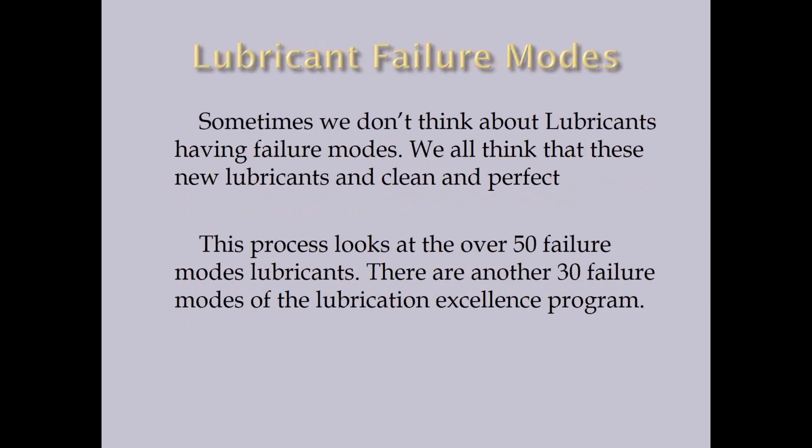Well, sometimes we don't think of lubricants as having failure modes, and sometimes we think if we buy a lubricant, it's in its brand new drum, it's coming, and somebody opens it from the customer that it's clean, but it's really not. Many lubricants that are in the drums from our customers actually have particles in them, they have moisture in them, which creates some of the failure modes, which we'll talk about.